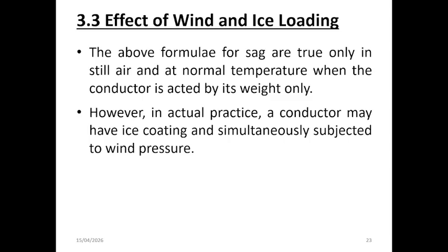However, in real-world scenarios, conductors are often exposed to additional environmental loads such as wind pressure and ice accumulation. Ice formation increases the effective weight of the conductor, leading to higher sag, while wind applies a horizontal force that can alter the overall loading condition.